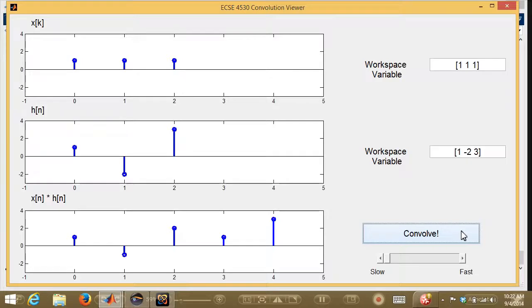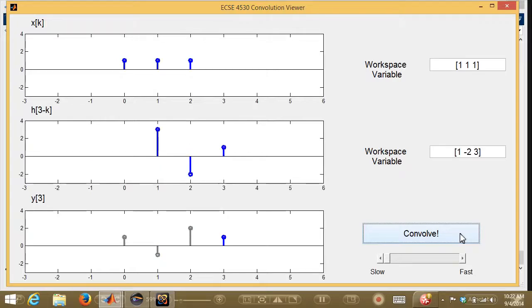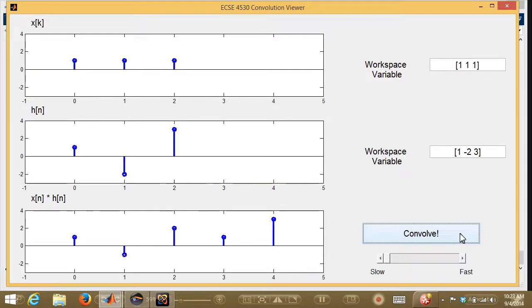Basically, this mirrors the same thing. In some sense you're not getting anything for free. You're doing the same computations that you had to do originally, but I don't know if it's easier, it's certainly a different way of imagining what's happening to the signal: this flip and shift. In the beginning there's little overlap. Then I slowly overlap with more of the signal until I fully overlap it. Then the impulse response starts to move off to the right-hand side, and I leave the signal. I'm really doing the same calculations as in the previous method, adding up shifted versions of the impulse response, but it's a more mechanical way of doing things.